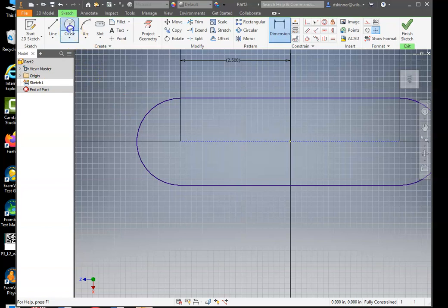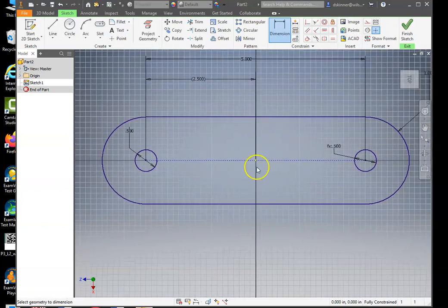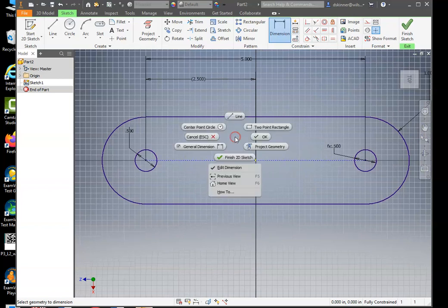I want to go ahead and extrude this with the hole in it, 2 holes. So that one is 0.5. This one is the same, but instead of putting a dimension, I'm going to click on the dimension and click the circle. And then instead of typing anything in here, I'm going to point to that and use the check mark. And it's always going to be equal to that other dimension. So I'm going to right click, finish sketch.